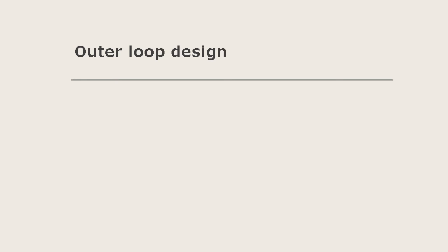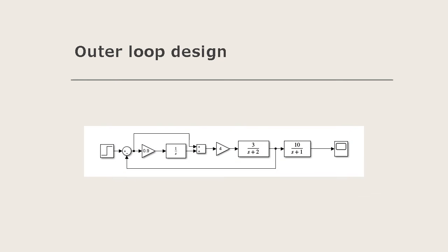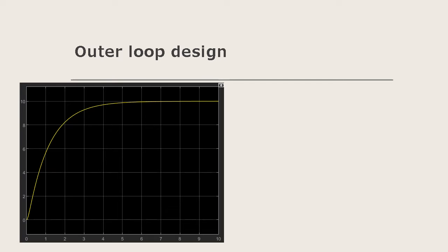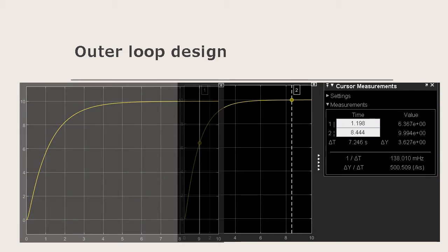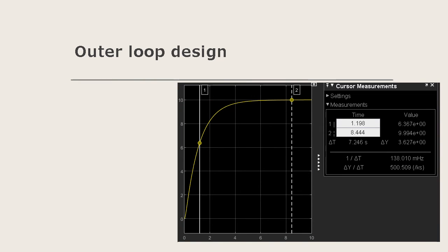Once implemented the system and inserted a unitary step input, the simulation is run, and as we can see, a response similar to a first-order system is obtained, which means we can fit the first-order model to the response. In order to do this, it is just necessary to obtain the final value, as well as the time in which the response is 63.2% of the final value. This is the definition of the time constant tau.